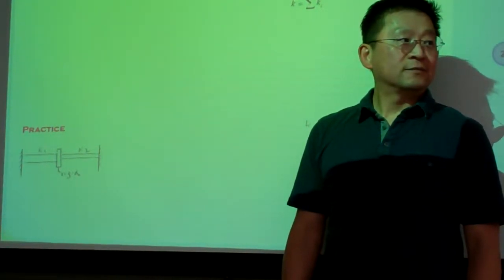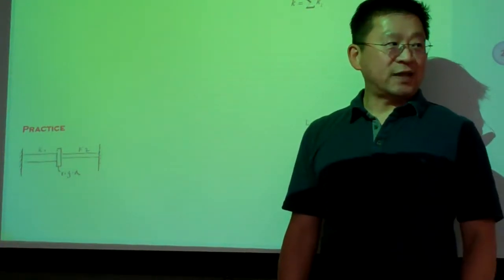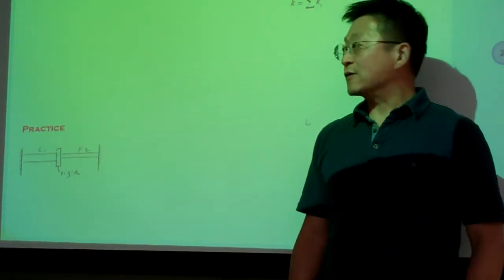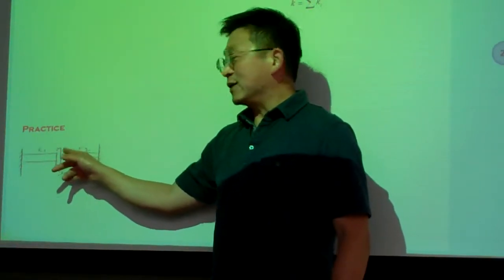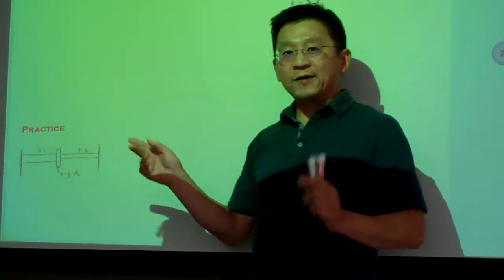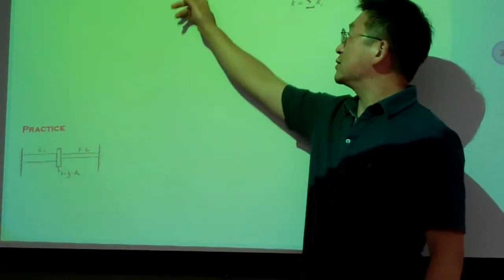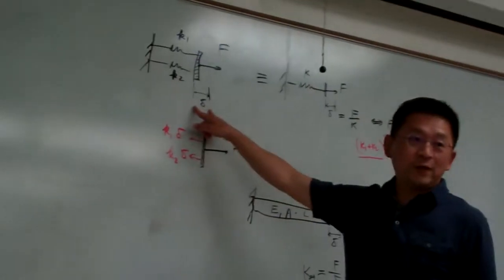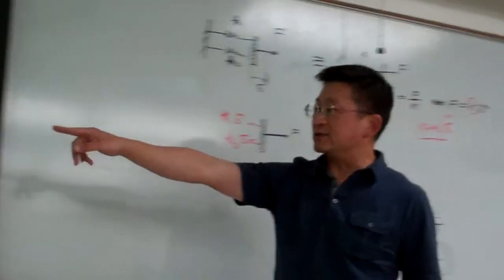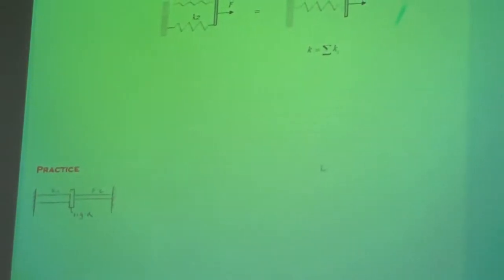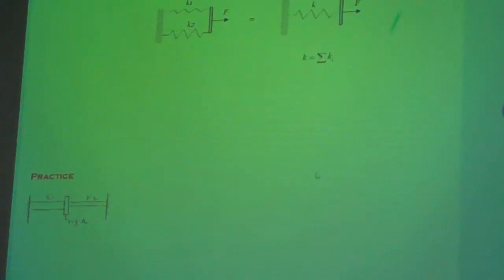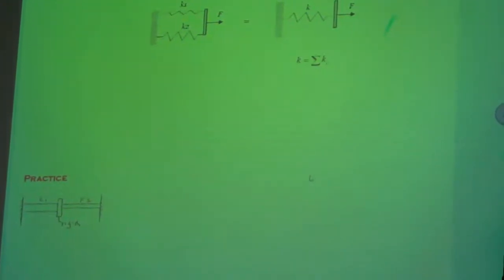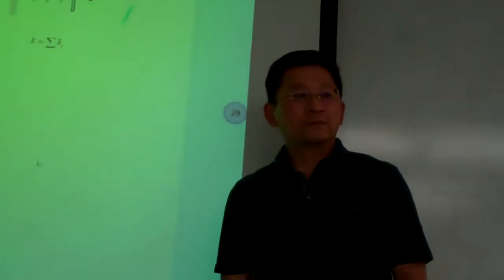They are. For one to deform, the other one has to deform, because they deform by the same amount. Although in terms of the drawing they look parallel, you stick with this notation here: parallel connections must have the same deformations. And this example fits that definition exactly. So don't be fooled by your eyes. Okay? You good?